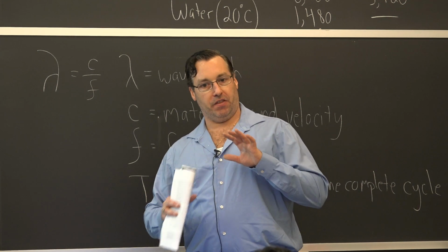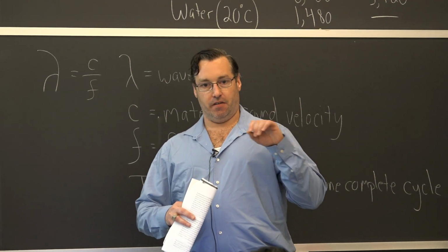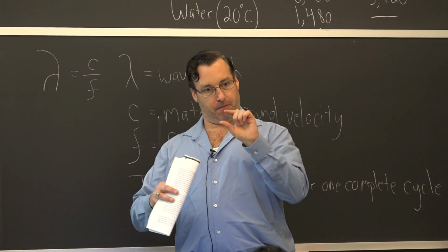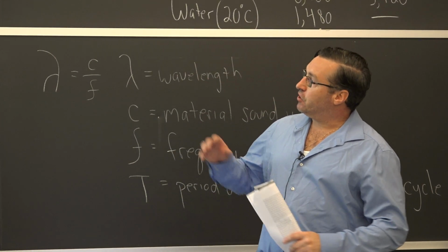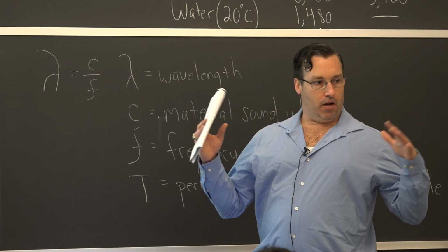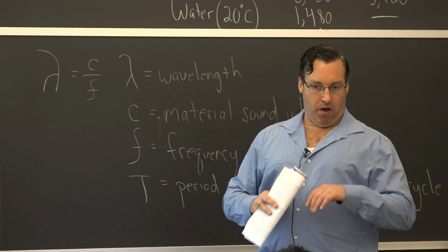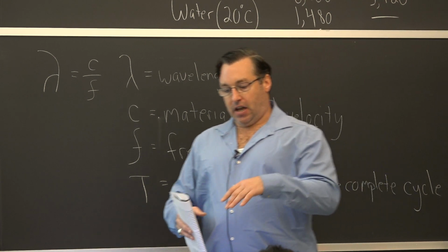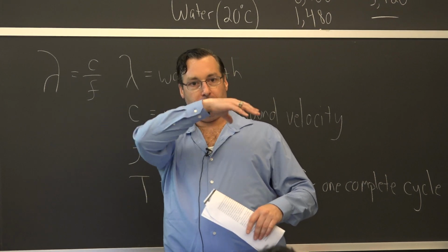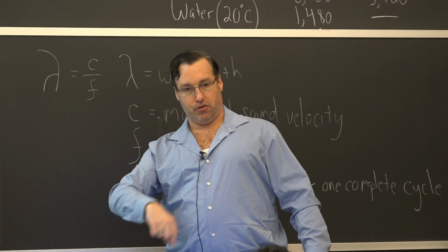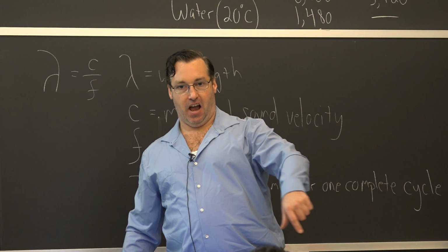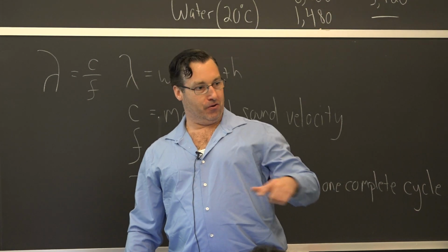There's ways to play around with that. If you use shear waves instead of longitudinal waves, you can try to catch flaws at different orientations. But in general, when you're thinking of ultrasonic testing for bridges or other components, if we're talking about rail, they actually have what's called a Sperry car, and it is a train car that sits on top of the rail, and it has ultrasonic transducers that point down at the rail right-of-way, and it does basically an inline inspection at night when certain train lines are out of service.